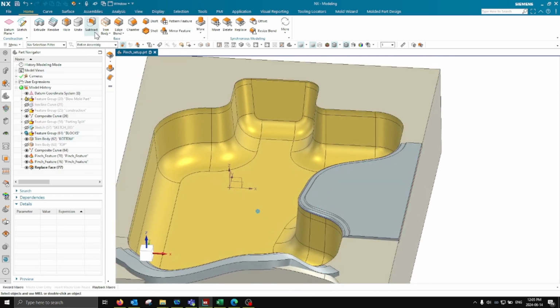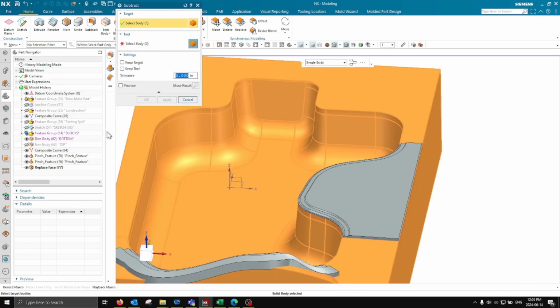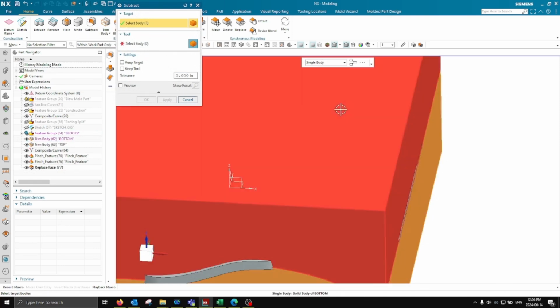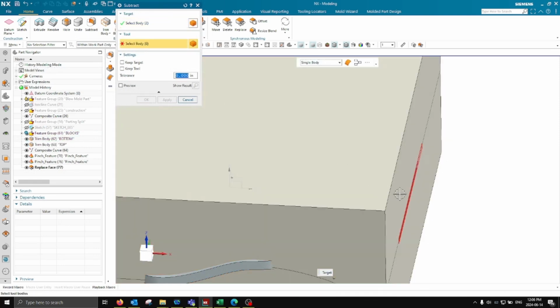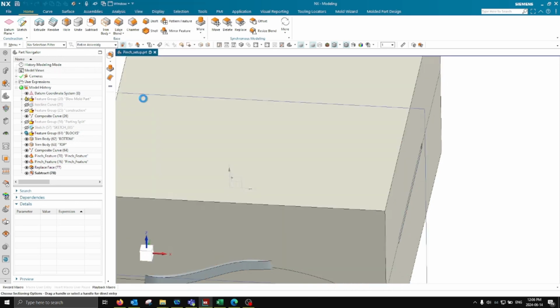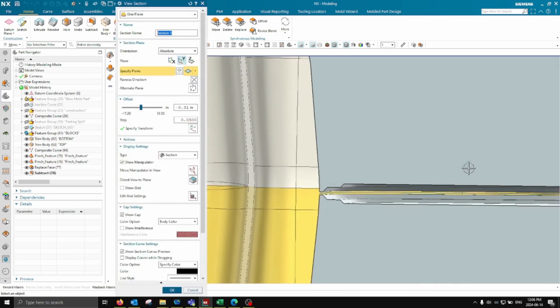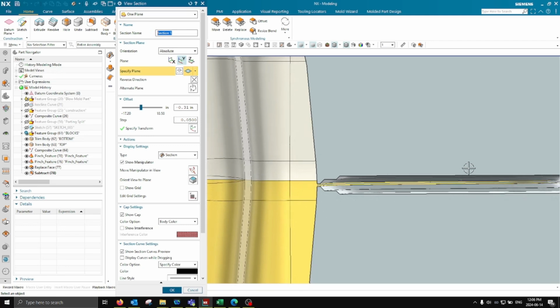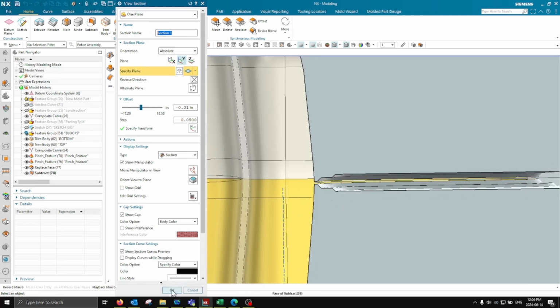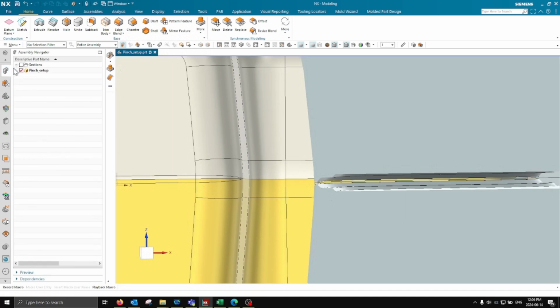And then what we can do here is subtract it from the two halves of this blow mold, so we can get a proper representation of the air gap that the pinch creates there. And then we'll cut a section using Control H, which is the hotkey for clipping sections here. You can see the pinch that we've created there. So small gap, and maybe it's multi-layer comparison. So we've got the multi-layer pinch there. And just to show the curves, we can turn those curves on in the section.